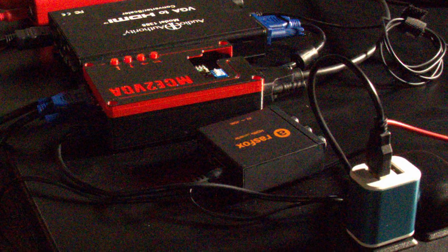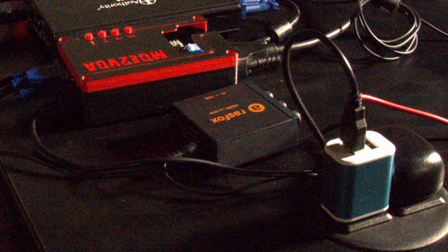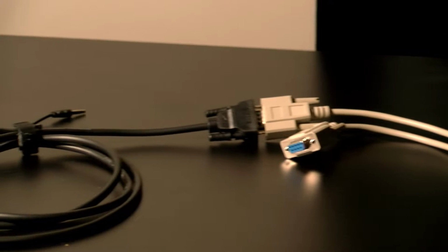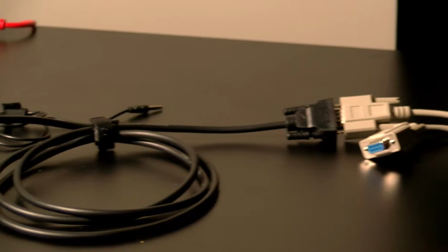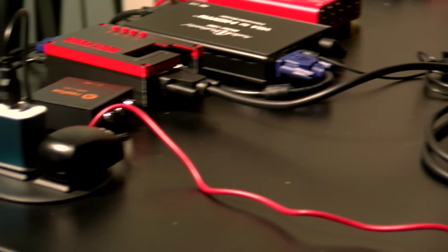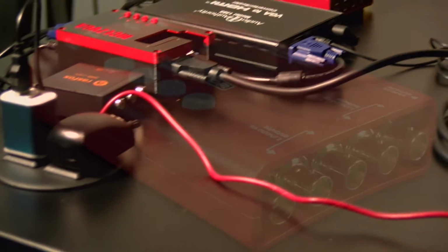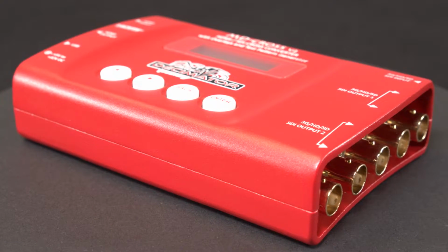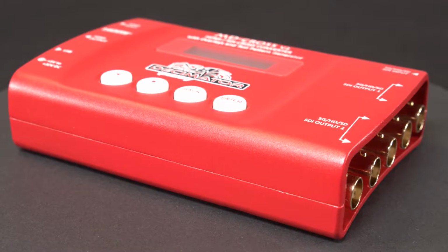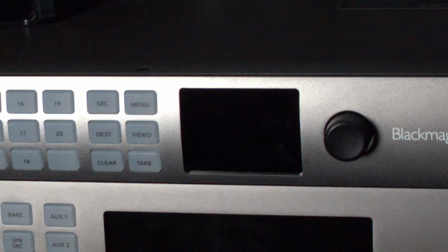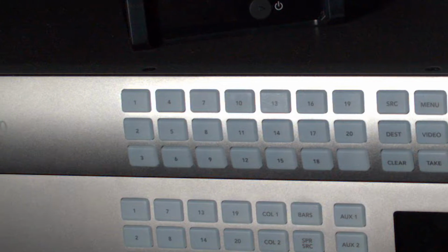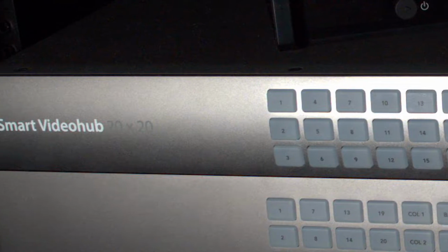Now comes the final step in the conversion part of the process. Whether originating from a RCA RGB source, a CGA graphics adapter, or VGA, we have converted the signal to full digital 1080p, being sent to our next stage using HDMI. This signal is sent to a device called the Decimator MD Cross V2, HDMI to SDI cross converter. The Decimator takes the HDMI signal and, if necessary, converts it to 1080p at 60 frames per second, which is what our video hub is set to use.